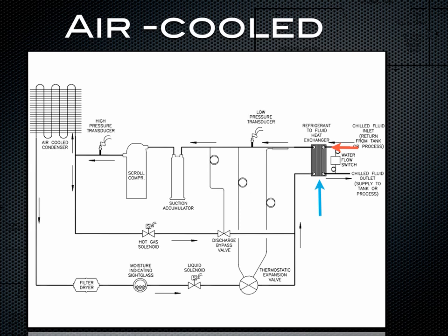How that works is through the second law of thermodynamics. The second law of thermodynamics states a hotter source will always move towards a colder source. So the refrigerant has to be colder than your desired leaving water temperature. So you've got your warm fluid coming into the chiller evaporator. The heat is transferred over to the refrigerant side. Then you will have your desired leaving water temperature back to your process. Go take a look at that video and you'll get a little bit better in-depth explanation.